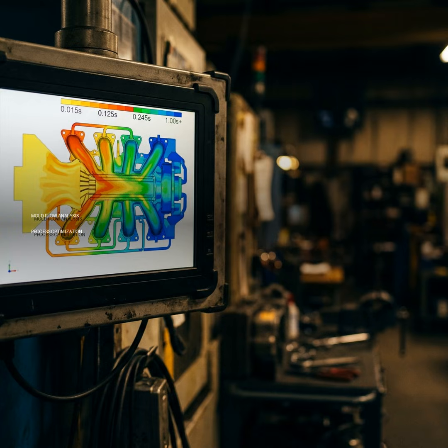What's next? After the mesh, it's all about material selection. Most software has databases with thousands of materials: thermoplastics, thermosets, even cooling media. You're inputting the material property model, things like viscosity models, PVT models, crystallization kinetic models, flow rate, specific heat capacity, thermal conductivity, mechanical properties.